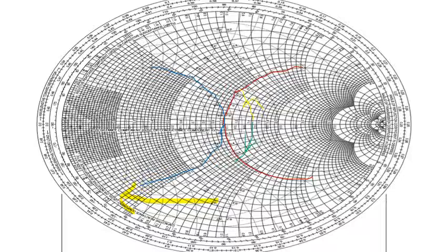So this is 0.8, 0.7, 0.6 maybe. You can take it over here. Yeah, this point we can take 0.6. Suppose we are going up. Can you all see this? I'm going up along the solid circle. So what will you plot? I went along the solid circle up. I'm going up, it has to be an inductor. Since it's a solid circle, it will be a series inductor.